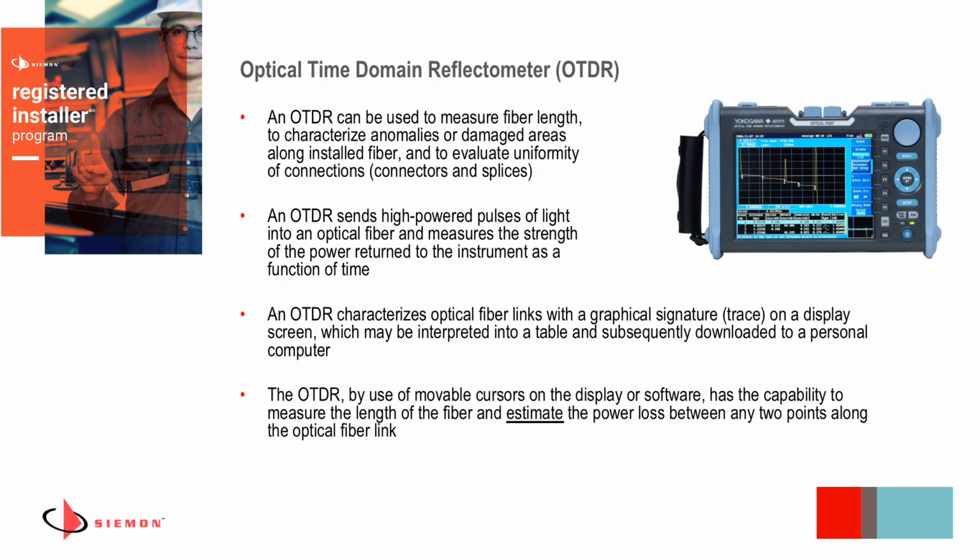Now, the other type of test equipment that's out there is an optical time domain reflectometer, or OTDR for short. These are much higher end systems than a standard optical loss test set because they provide a little bit more characterization of the fiber. So you don't just get a loss number, you actually see the loss events across the overall system. It provides a trace of the fiber cable, and it gives you an idea of the distances where these events occurred and what they are along the way. They're a little bit more complex to operate, in fairness, than an optical loss test set, but if you're looking for characterization, it's absolutely essential. Some OTDRs may even have an optical loss test set capability built into them, but as a rule, you can't use those alone for measurement of loss testing.